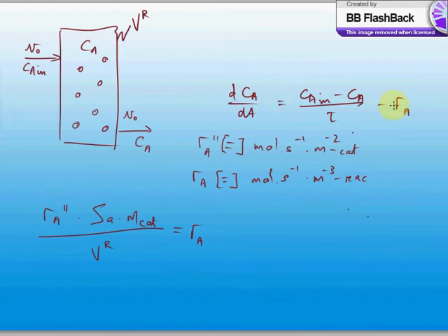This thing is quite familiar to us. So we need to unpack this Ra double dashed. So Ra double dashed, that we can get from the kinetics. So that's normally supplied to us. Let's say it's a first order reaction. We've got some rate constant there, and then we have to multiply with the concentration of A in the particle.